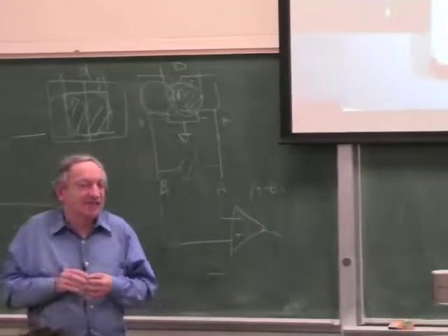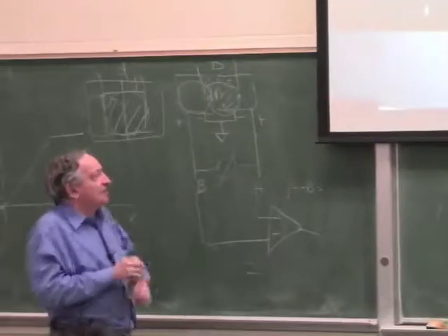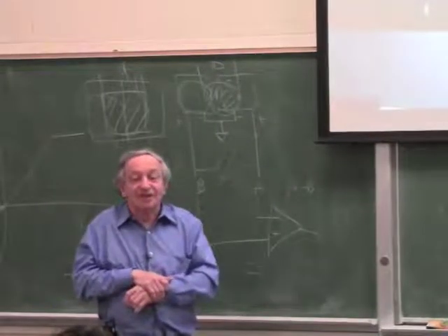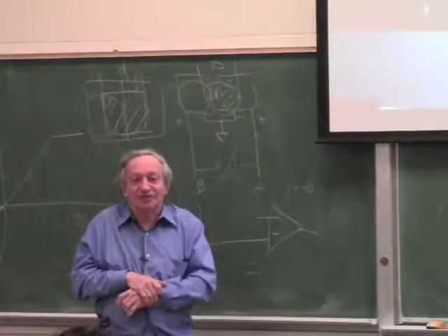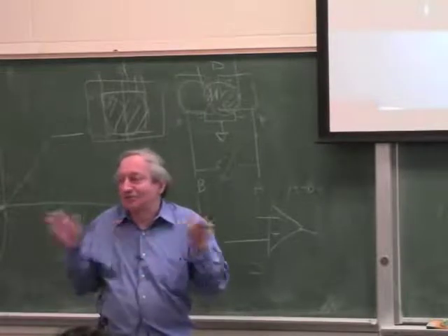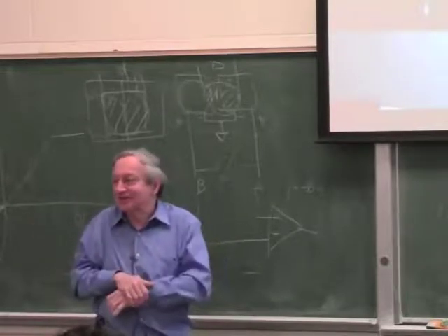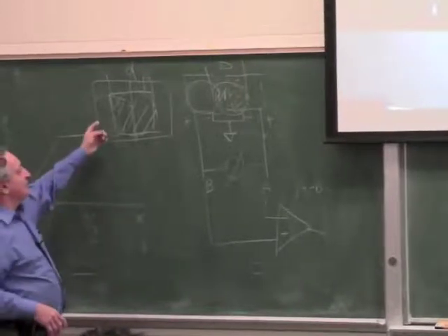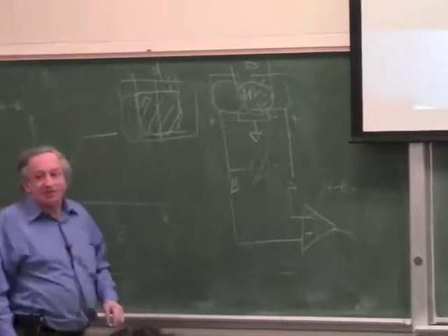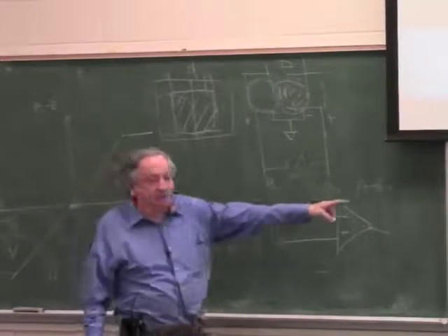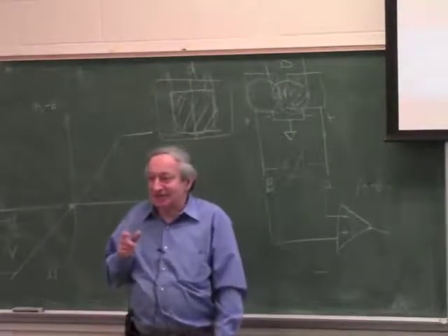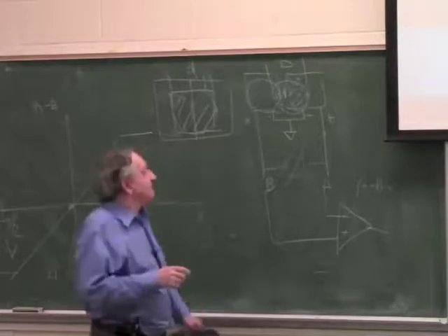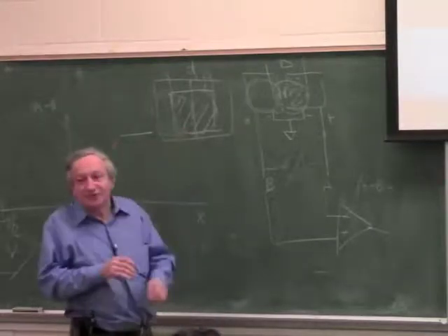So optical sensor, because the image can be scaled to any size, then it's a huge advantage. You can take one detector and use it for all ranges, for all sizes, and you can convert this to an angle detector, or you can convert this to a displacement detector, just like I explained before. Depending where you place this lens, this can become either an angle detector or anything you want.